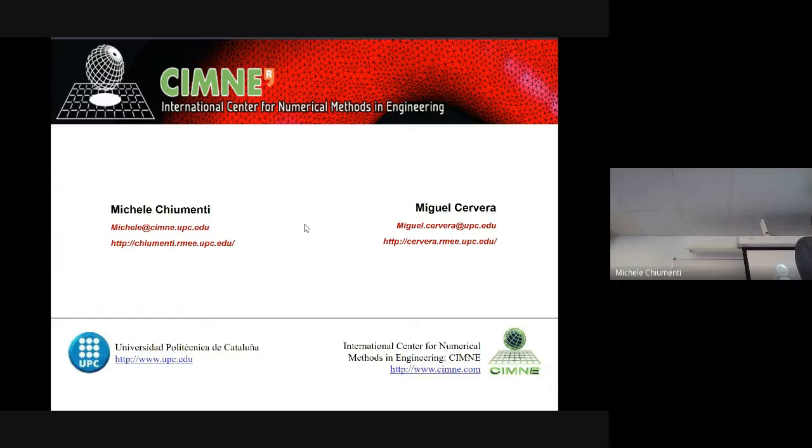If you have a finite element which includes more degrees of freedom, it allows you to do more things. It is more powerful, with more options. In particular, if you have pressure control, you can control the pressure instabilities. If you have strains, you can contribute to the accuracy of the solution in terms of strain and stresses, and particularly to catch the direction of the cracks.